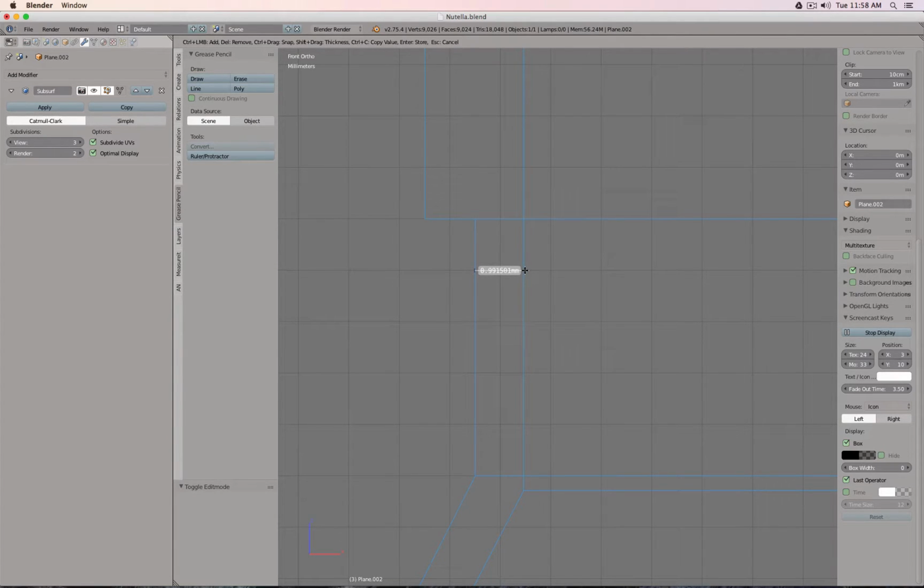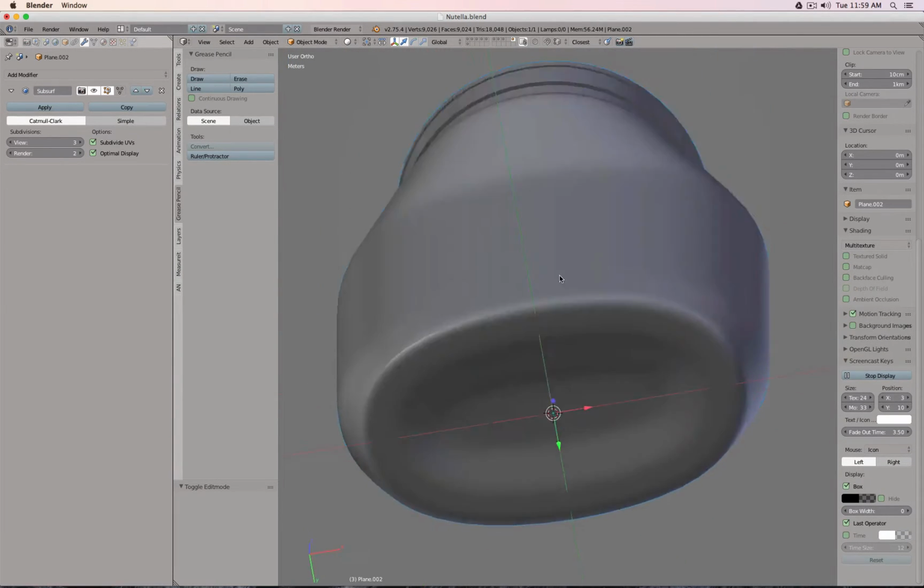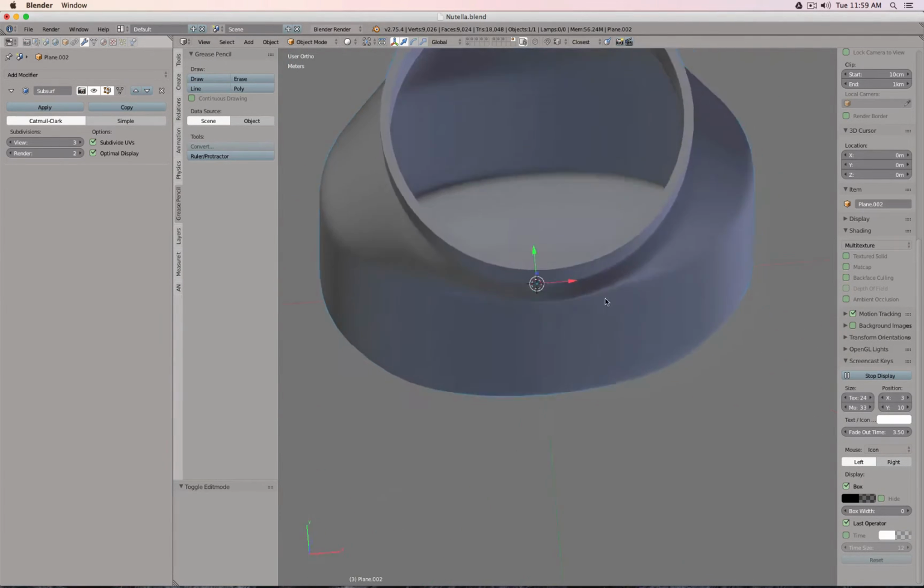Yeah, okay, so we don't really want to get this line further to the 2 millimeter mark, because then here we make it even thinner. If, for example, our target is that the lower part of our bottle remains roughly 1 millimeter thick. Okay, so that's actually fine.